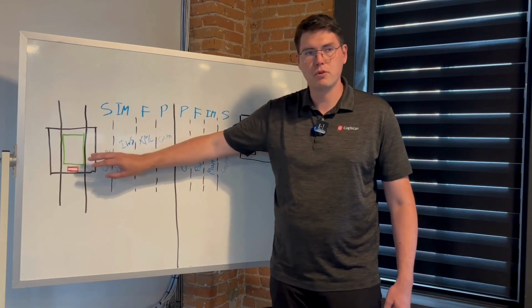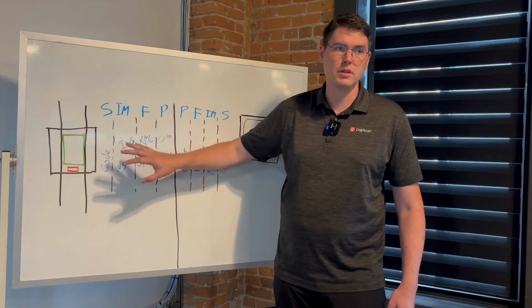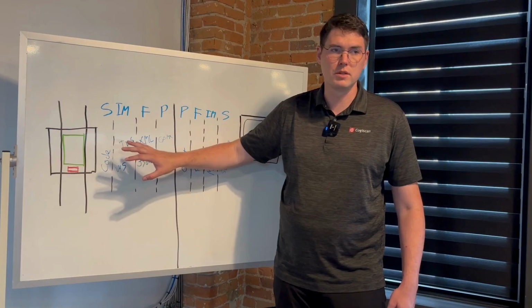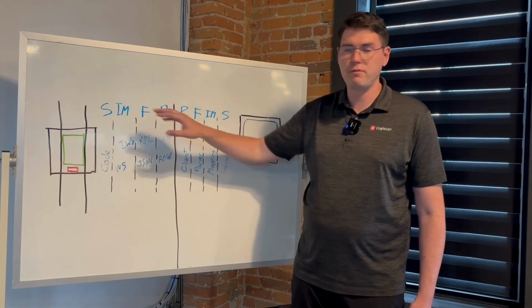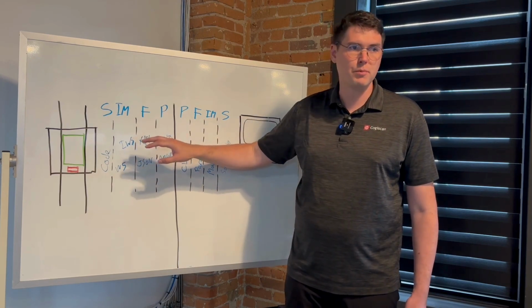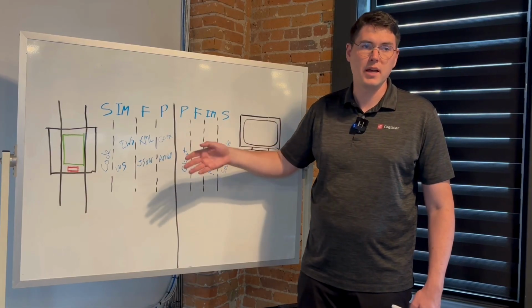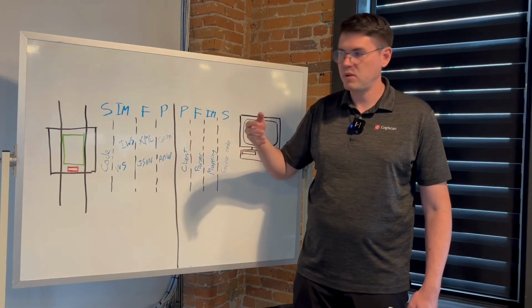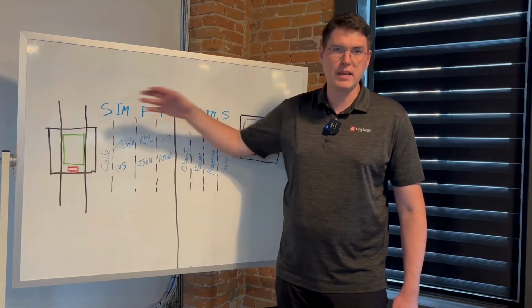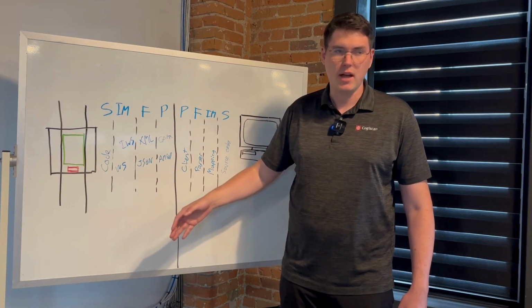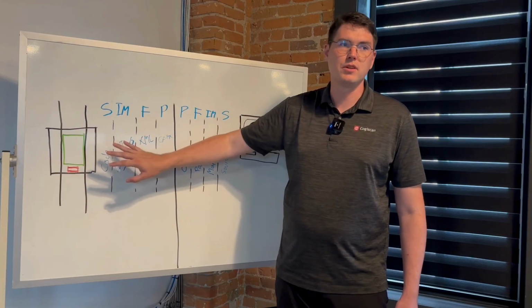The sensor would probably send out an error, and then the source code would decide what to do. So the source code would say, okay, if I detect an error on the barcode reader, I will output fail in the information model. And that's really just one case, but the thing is, you have to know how the machine will react for every case that can happen on the machine. And because this is hidden and proprietary, this is where the difficulty is.